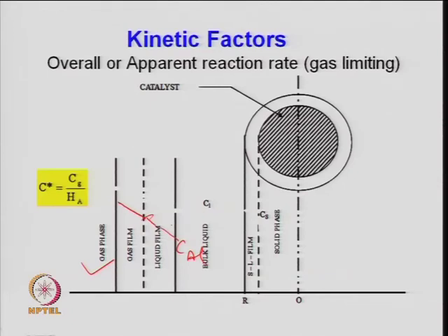So, that is what I said, that depending upon the resistances, whether it is K_AG or K_AL, that is the mass transfer coefficient, how to enhance those mass transfer coefficients? The correlations are available, because it will depend on the property of the gas, the property of the liquid, and also on the shape and size of the solid.